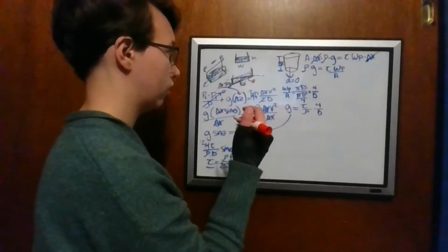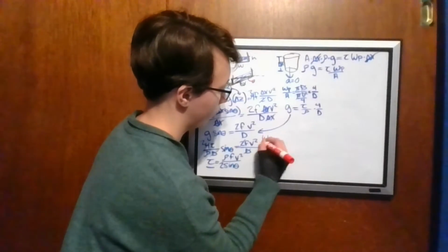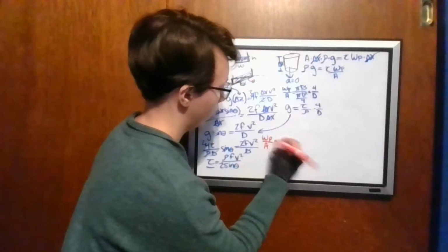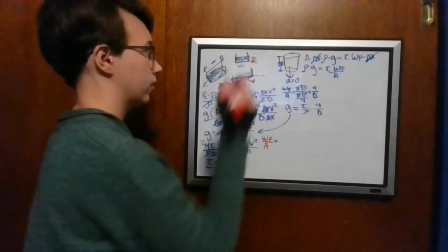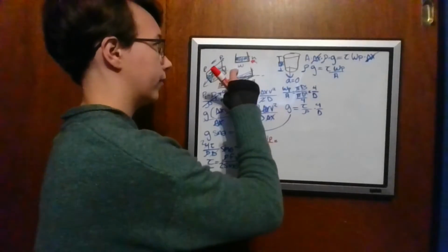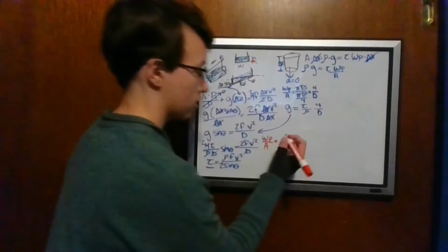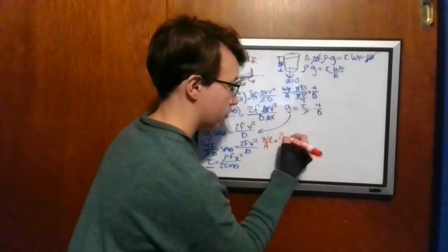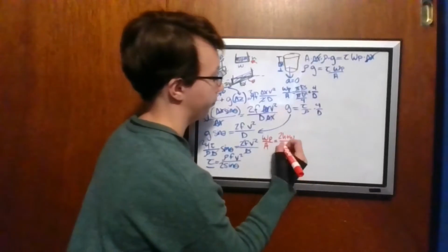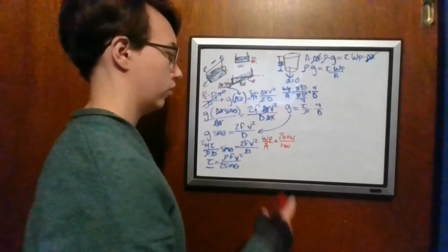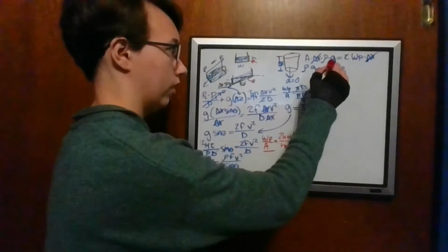So we can do that down here, where we have the wetted perimeter over the area. From that, we're going to look at this side most closely. So our perimeter is side length h plus w plus h, so that's 2h plus w, and the area is just h times w. Alright, so we can plug this and this into this equation.